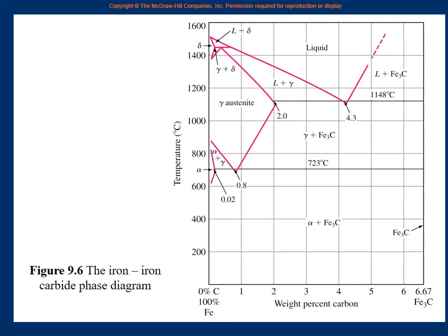So this is the iron carbide phase diagram, which means that it is the phase diagram for plain carbon steel, right? Plain carbon steel. When we have added only carbon to the steel, we have not added any other alloying materials like manganese and so on. So if you want to give it a name, it is a binary non-isomorphous diagram, right?